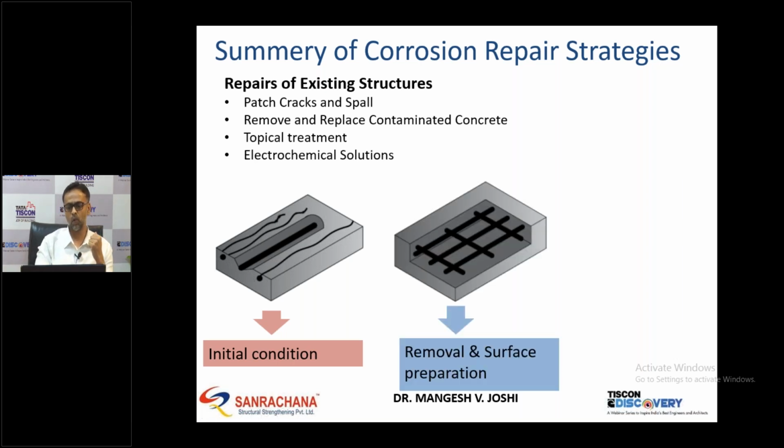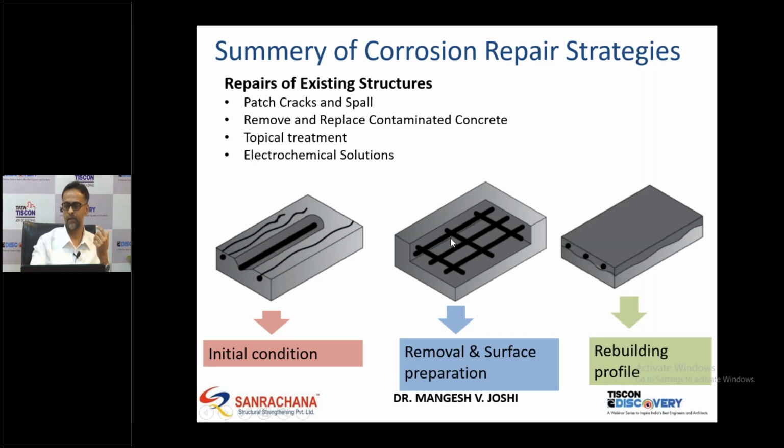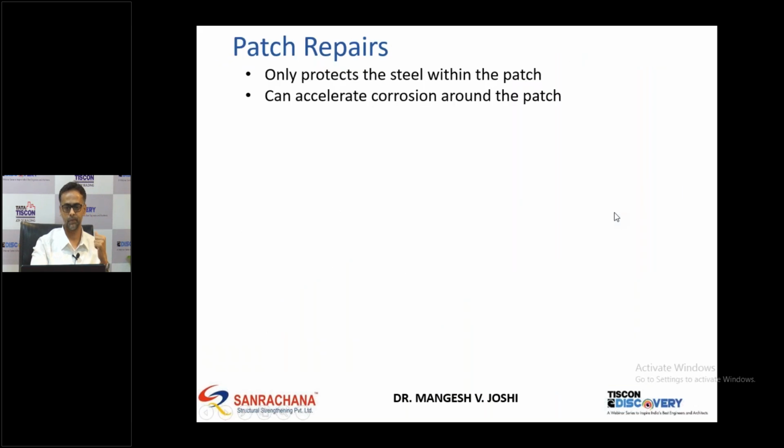Ideally, we should remove all the contaminated concrete, like shown in this slide. Remove all the contaminated concrete, and then we can rebuild the profile by using different chemically activated mortars which are available in the market: polymer modified mortars, micro concretes, grouting, or whatever is best suited for that particular situation.